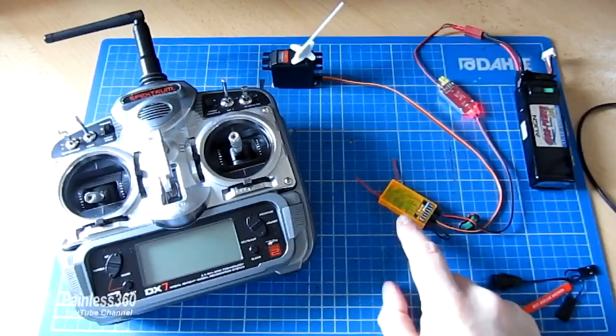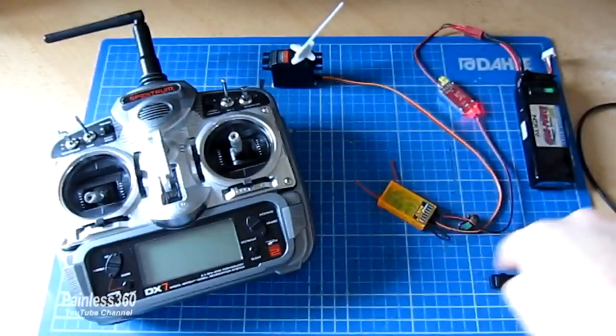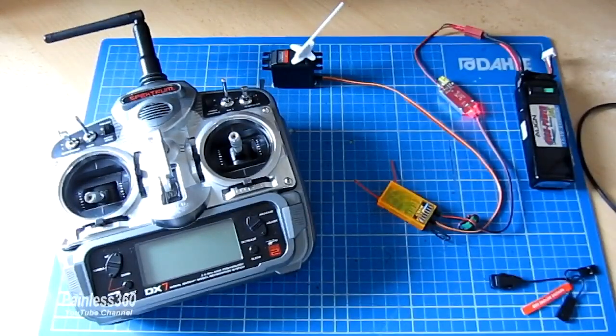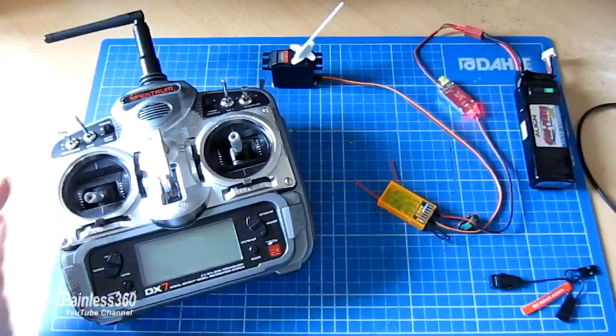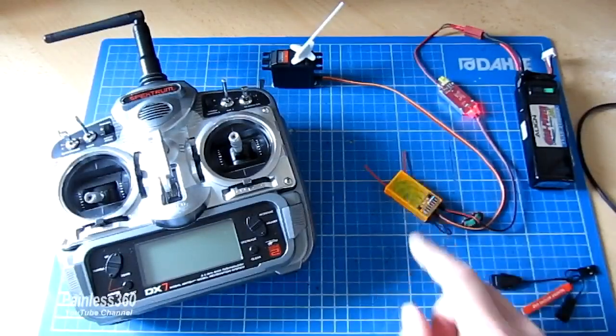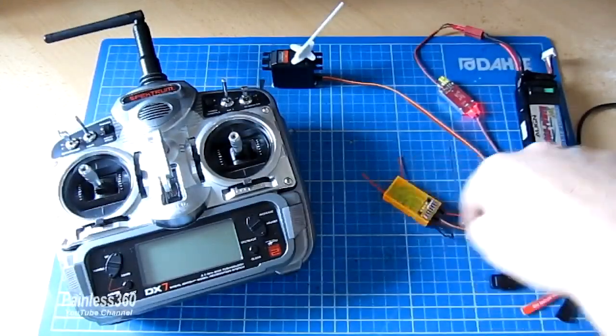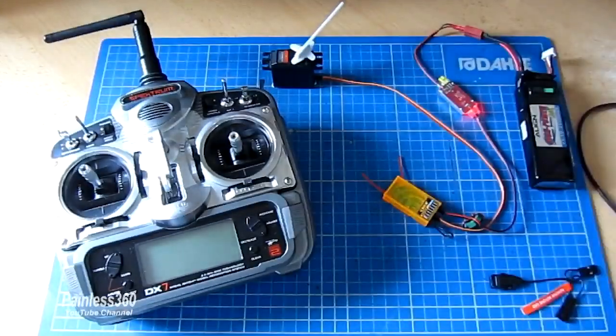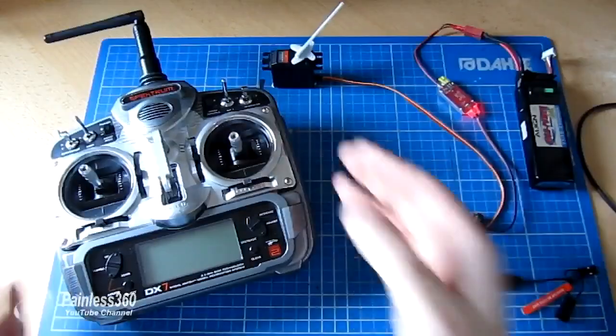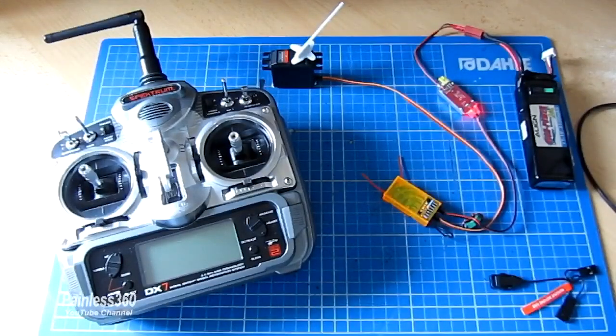If you don't have it, the danger is that the radio continues to send the signals that it had when the connection was lost. If you were at full throttle in a dive when the radio went off, the model will continue full throttle in the dive right until it hits the ground. And you'll occasionally hear about something called flyaways on the forums, and that's sometimes what will happen. If the radio connection is lost and there is no failsafe set up on the receiver, then wherever the sticks were when the radio connection failed, the receiver will continue to power the servos and speed controller at that level and those positions, and continue to fly the plane right out of sight and right out of your life.